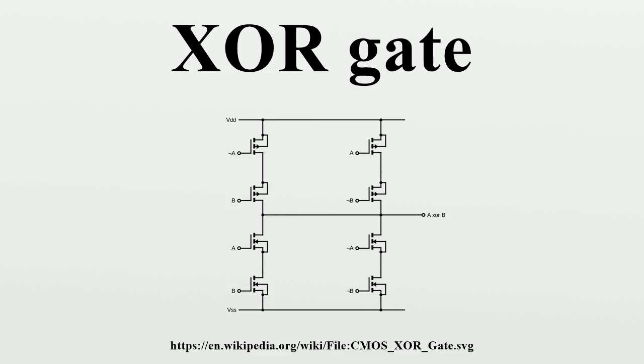Implementation. Using pass gate logic wiring, an XOR gate can be constructed using MOSFETs. Here is a diagram of a pass transistor logic implementation of an XOR gate. Note: the RSS resistor prevents shunting current directly from A and B to the output. Without it, if the circuit that provides inputs A and B does not have the proper driving capability, the output might not swing rail to rail or be severely slew rate limited.